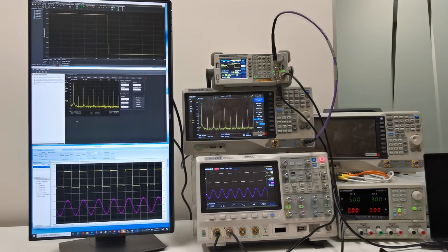The reason I want to use a square wave as an example is that you can see the difference and the connection between the time domain and the frequency domain. In the time domain, we have a very sharp rising edge and falling edge. And in the frequency domain, we can see a lot of higher frequency components in the spectral analyzer. We can see more power in the odd multiples of the frequency and less power in the even multiples. And that result actually matched what we learned from the Fourier series of the signal. Okay, now it's time to have some fun and make some noise.